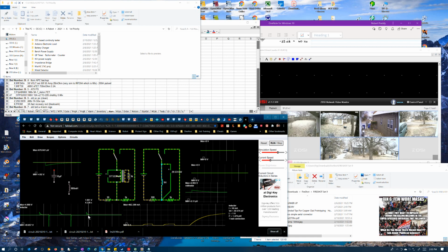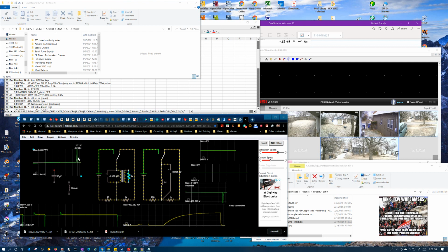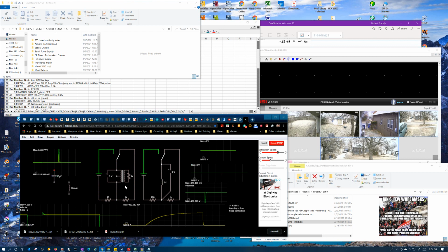Whereas normally it was charging and discharging like this over here, down to about 100 millivolts here. Now let's try to flip it. Okay, see, now instead of 24 volts, we're getting 240 volts over here, but we're dealing with a lot more energy. Like I said, the amount of energy you have stored in the inductor has a big impact on the actual voltage spike you see.